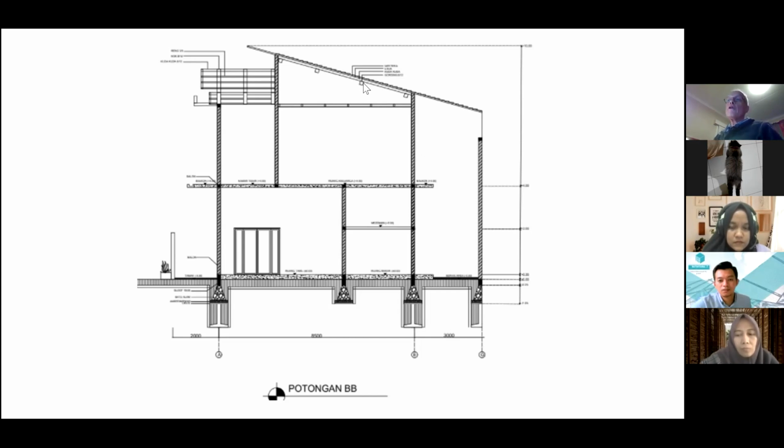So you can see that we've got a problem with the roof structure because the student hasn't understood the principle of spanning the shorter span when you have a choice.